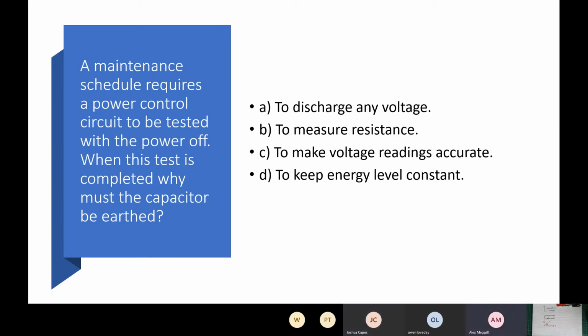Yes, a capacitor is a device that holds a charge. It's a bit like a very small rechargeable battery. It will actually hold electricity for a very short period of time. So we use it for smoothing, for instance, where there's a lot of ripple current, where the current's going up and down. The capacitor will charge when the current's high and discharge when it's low to offset it and smooth it out. So a lot of devices have got capacitors on them for smoothing.